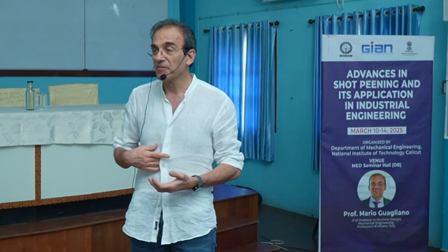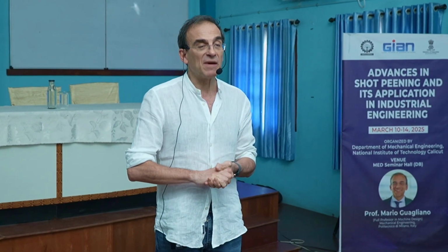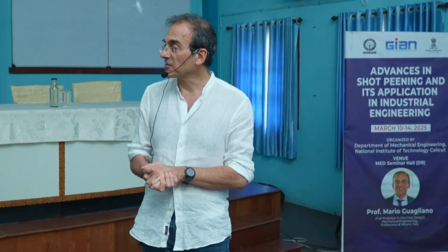And then we will also introduce the other methods that we can use, the hole drilling method especially, and the Barkhausen method, which is based on the measurement of the magnetic noise, and can also be used for the measurement of residual stresses.